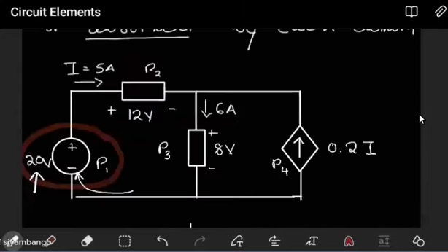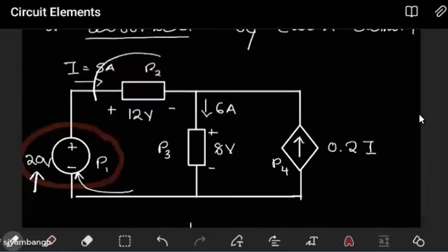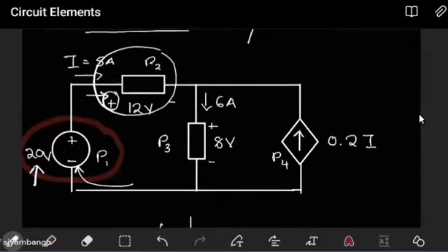And when you look at this resistor, notice that using that trick, it works, because for this resistor the current approaches the positive terminal first, meaning that here it's going to be plus. Basically, all you want is: resistors absorb, so positive; sources give out, so negative. Okay, so this is going to be positive first.